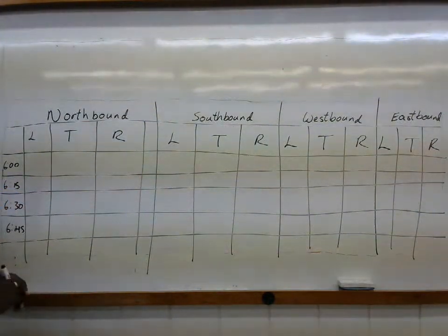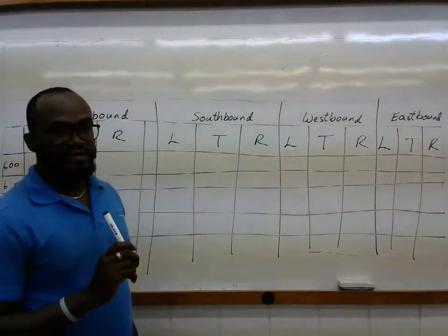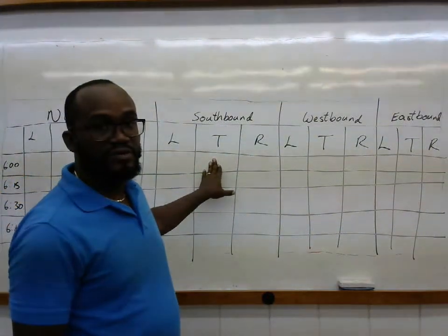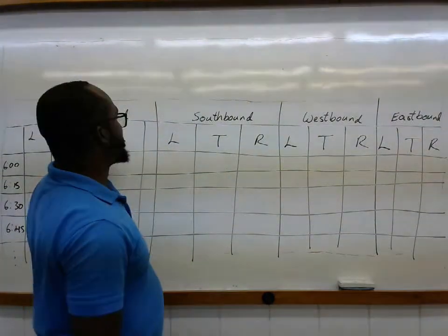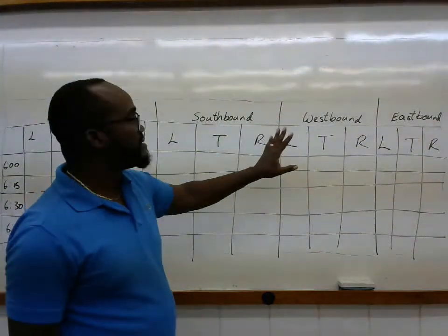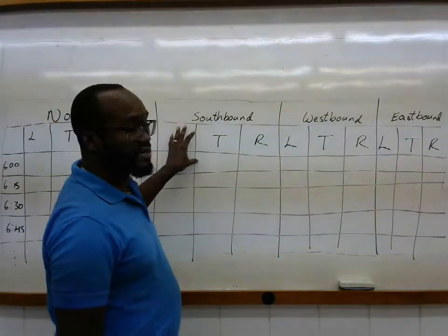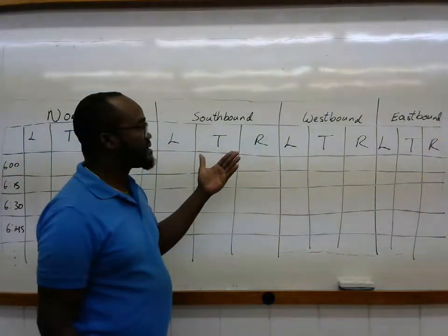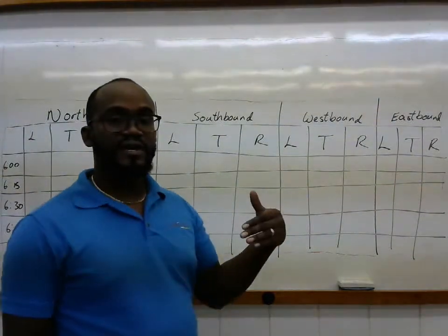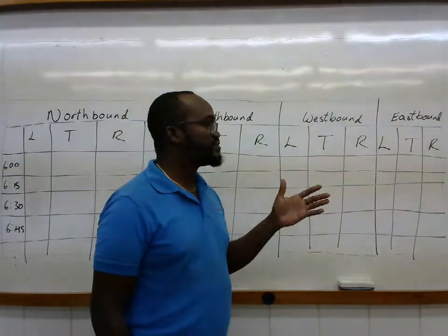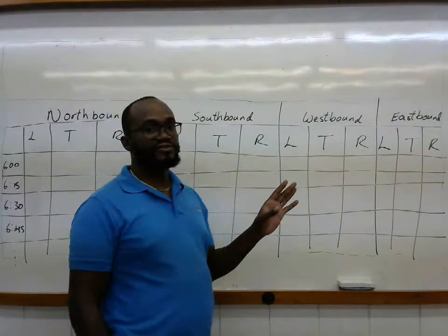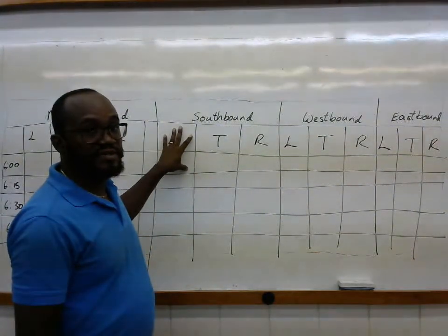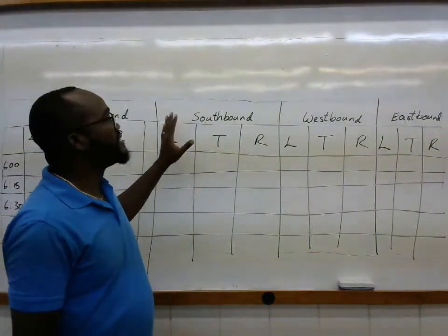Now, please note that we are doing a classification count. So the way the software works with the counter is that a sheet like this will be generated for each class of vehicle. So for class 1, I'm not too sure what you all use, but the class 1 was cars, class 2 was small maxes, etc. But essentially for the 6 classifications that were undertaken, including pedestrians, you will have these sheets.